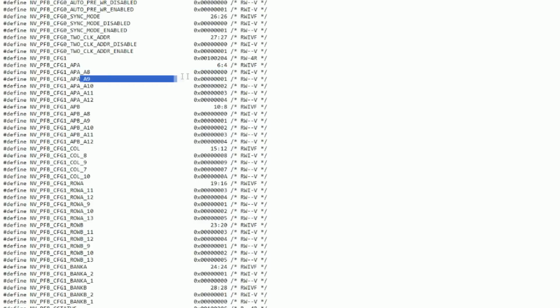And what's nice is I can change that. I do have some choice to change that auto precharge pin. You might think that this is not very useful because we want it on A8. If I switch it to A9, then it is on the wrong pin. This is not useful. However, because of the nature of addressing, we are basically free to change pins. If I switch A10 and A11 in the hardware, then this is no problem at all.